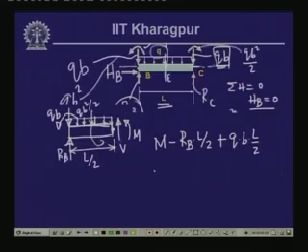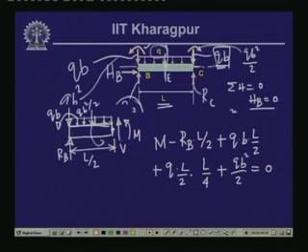So, that is positive. So, that is Q times L by 2 times L by 4, half the distance, and we have this moment which is in an anticlockwise form, which is QB square by 2. So, these are the moments which we have, and this is equal to 0. Now, we have seen the value of RB is equal to QB plus QL by 2.